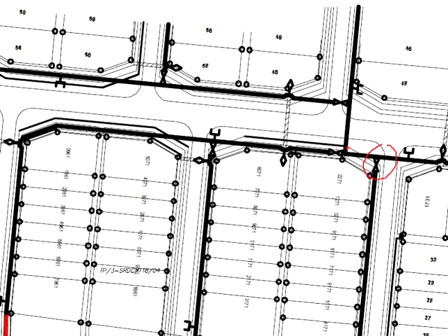Normally, there will be switch valves at the junctions of the water reticulation system. They are strategically placed at the junctions, so that if any part of the water reticulation system requires maintenance, the nearby switch valves can be turned off in order to minimize the disturbance of the water supply to the units of the other regions. This is about the simple principles of adopting the switch valve.